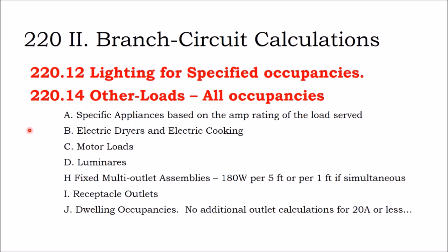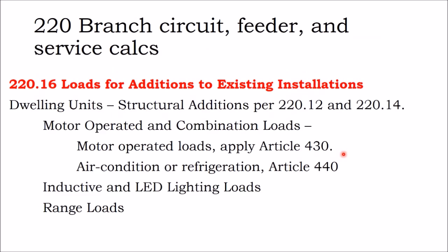So if you're building a tiny house and you want to have a well-sized electric panel, a code-compliant tiny house, you might find that you have to go into this section and calculate a dryer or a motor load of National Electric Code. Now, you could also get an electrical engineer to review it and go by an engineered calculation and not necessarily use these code values.